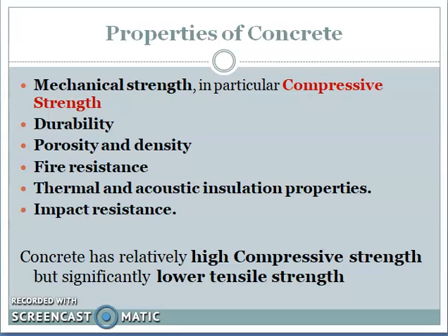Concrete has very good properties. So to list few, first is mechanical strength, in particular compressive strength. Second is durability, porosity and density, fire resistance, thermal and acoustic insulation properties and impact resistance. As I already mentioned, concrete has relatively high compressive strength but significantly very low tensile strength.